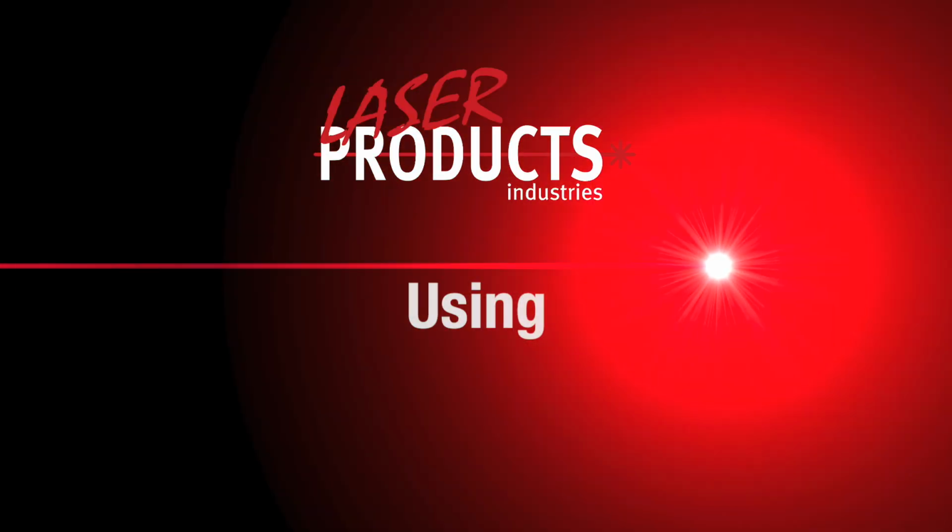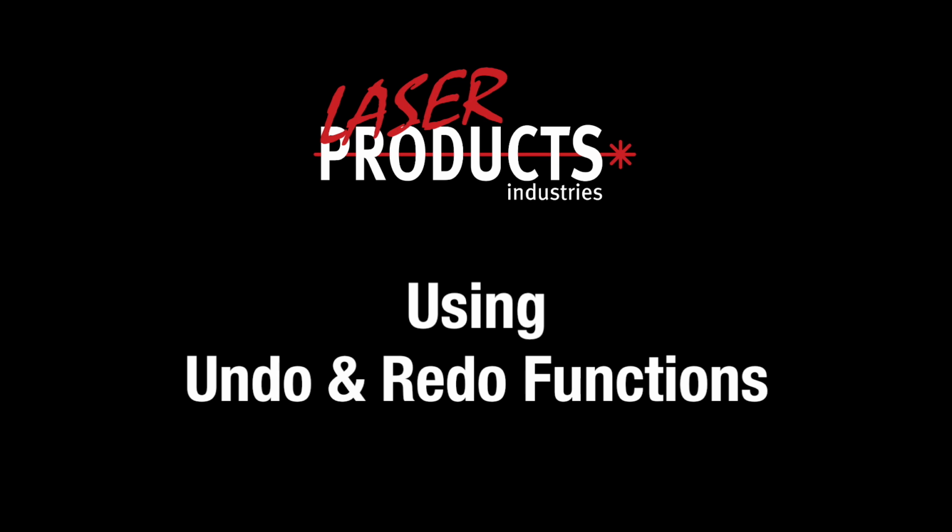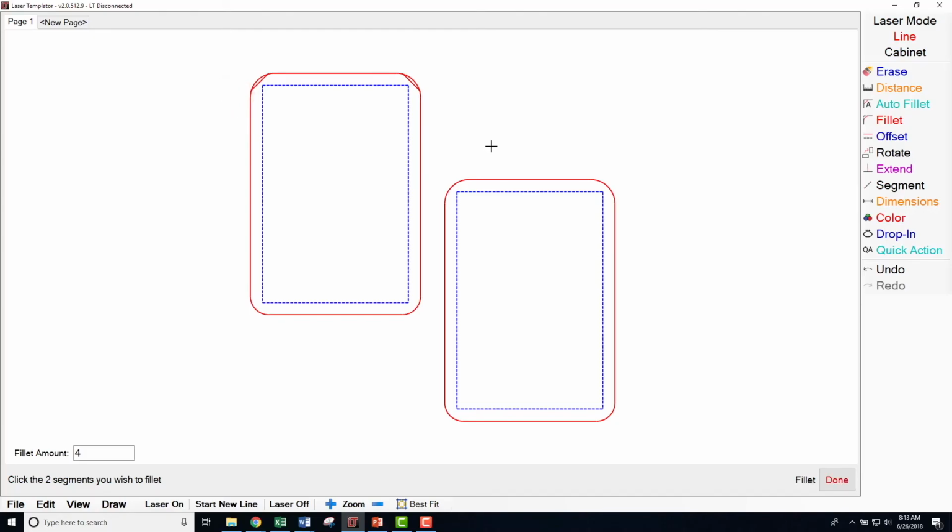In this video, we will show you how to use the Undo and Redo functions. Undo removes the last action taken and can be used for virtually every function in the Laser Templator software. The Undo function allows you to remove up to the last 20 functions completed. If you accidentally undo too many functions, select Redo to bring back the unintended undo function.